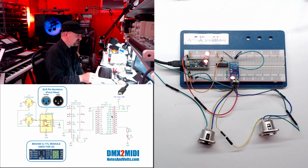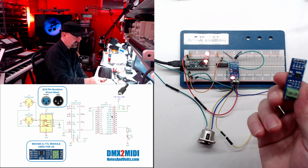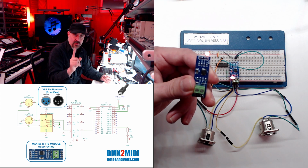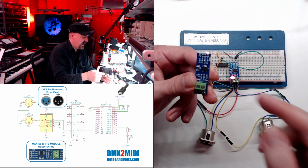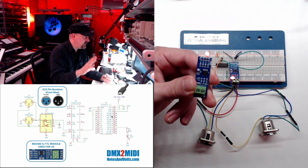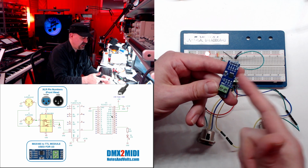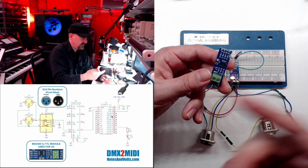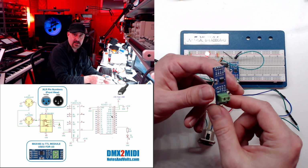So to handle those messy DMX signals, we're going to use this little guy here. Now this is called a MAX485 to TTL module. The MAX485 chip has one job, and that is to take those messy RS-485 signals and turn them into a lovely and polite 0 to 5 volts TTL output. Now these modules I found on Amazon contain the chip and a bunch of support components, and they're very cheap. So I thought instead of trying to rebuild this whole circuit, why not just get a bunch of these and just call it a day.